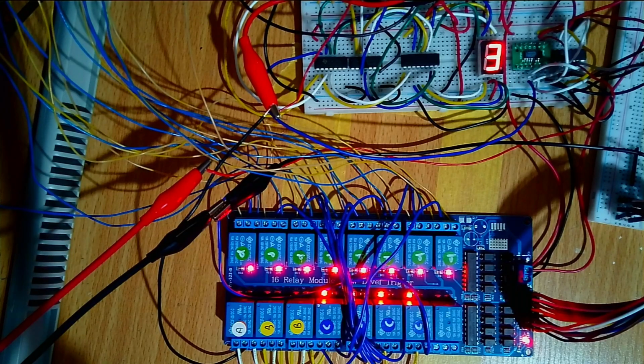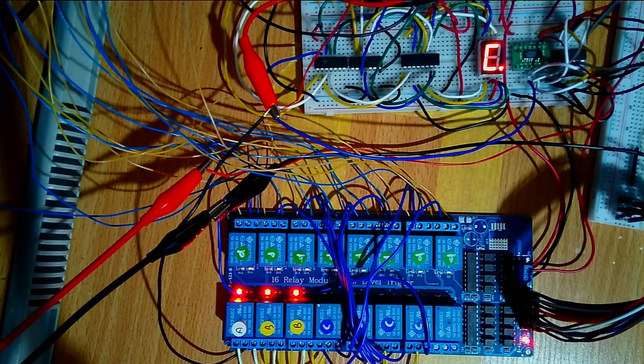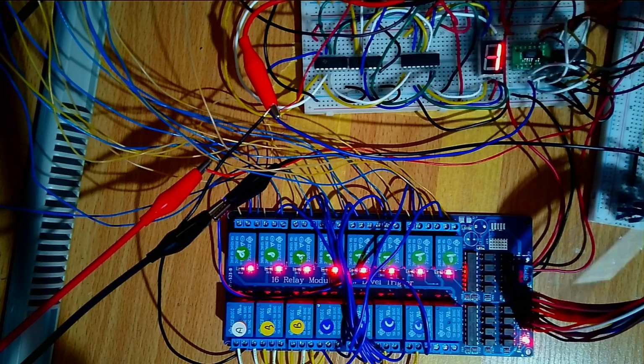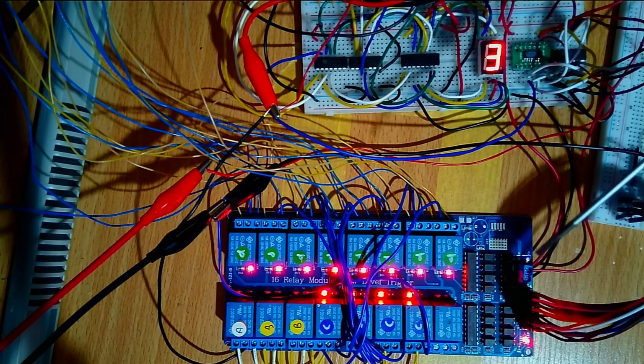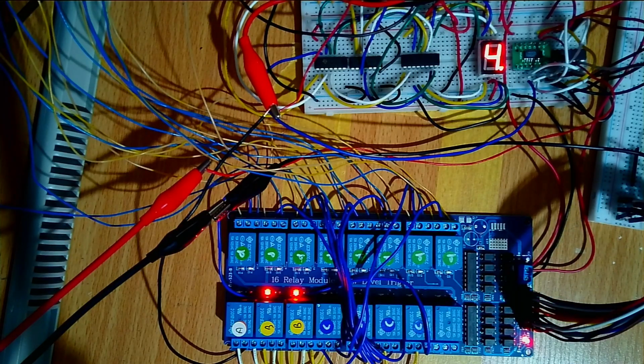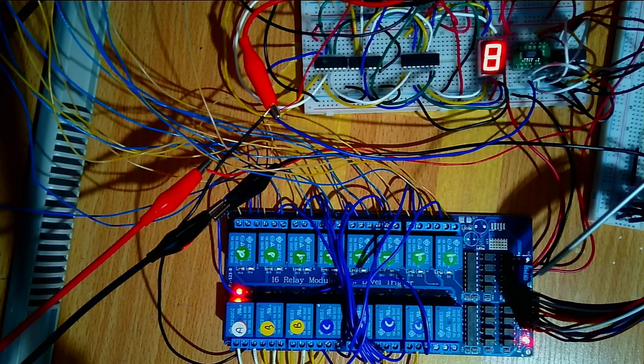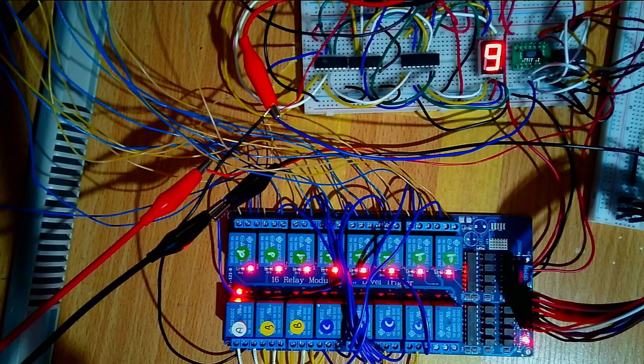I finally figured out how to get the lights to light up properly. The problem was, at some point I'd changed the frequency of the sine wave going through the coils, or the cores of the coils, and that sort of detuned the comparator circuits. So I've just bumped the frequency back up, and I think it's about 5 kilohertz now, and it works, as you can see, much better. This is pretty awesome now. Pointless, but awesome.